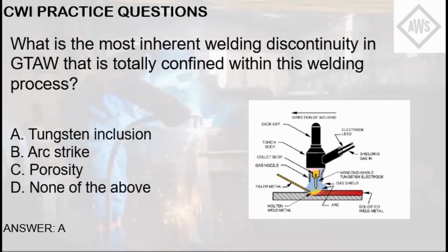Basically, there are processes that can be automatically pre-qualified without qualifying in a PQR. GTAW is one of those processes that cannot be automatically pre-qualified. You need to abide by the qualification process of clause 4 of AWS D1.1.